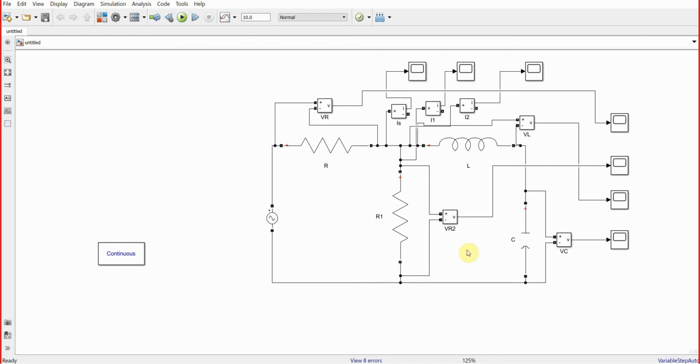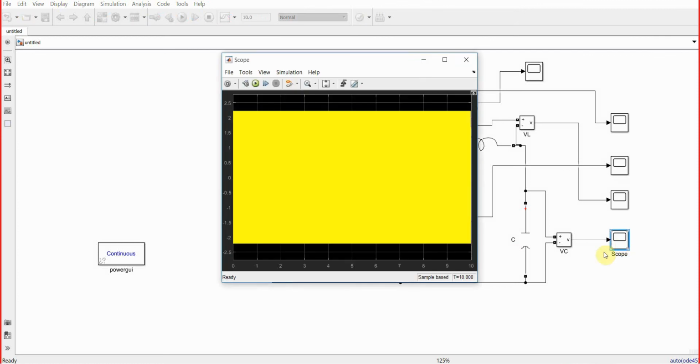So your objective is just to run the electrical circuit. You have to include this block first, then you're gonna run. So now we are in good shape, and once you hear this hit, it means that it is done. Now if you click over any one of these scopes, you're gonna end up with the figures, results. But as you can see, the voltage over this capacitor is barely seen, like it is a single block, but originally it should be a wave.